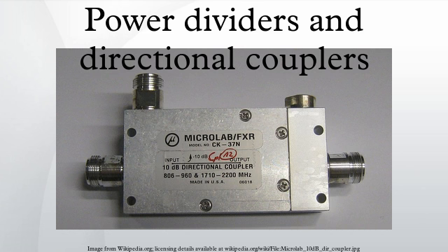Wilkinson power divider. The Wilkinson power divider consists of 2 parallel uncoupled λ/4 transmission lines. The input is fed to both lines in parallel and the outputs are terminated with twice the system impedance bridged between them. The design can be realized in planar format, but it has a more natural implementation in coax. In planar, the 2 lines have to be kept apart so they do not couple but have to be brought together at their outputs so they can be terminated, whereas in coax the lines can be run side by side relying on the coax outer conductors for screening.